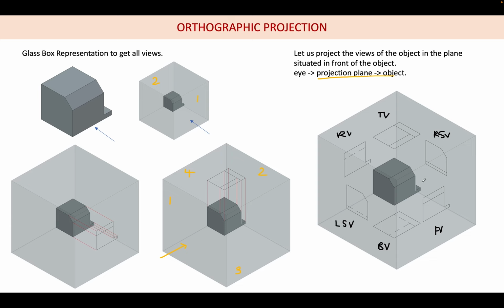If you try to see the front view, you are able to see this edge. I am saying this is the edge of interest. In the front view you are able to see the edge, but in the rear view this edge will not be visible if you are looking from the back. So, what we do is represent this edge as a dash line, which means that it is hidden. Last class we saw some standards based on the types of lines to be used. I told you that it is available in SP46. If you check, you have different lines for different situations.